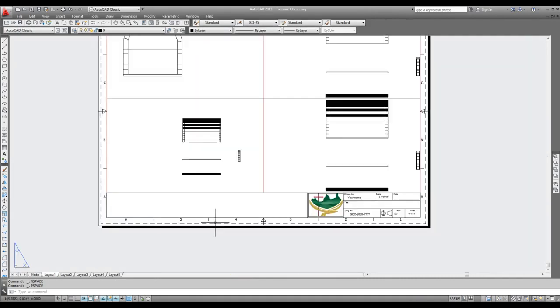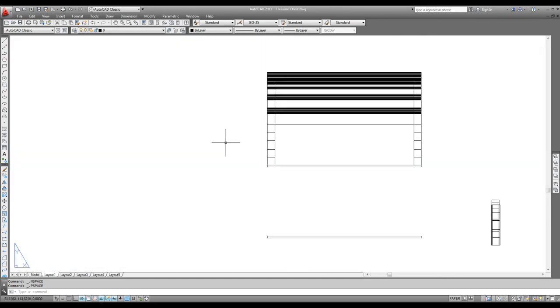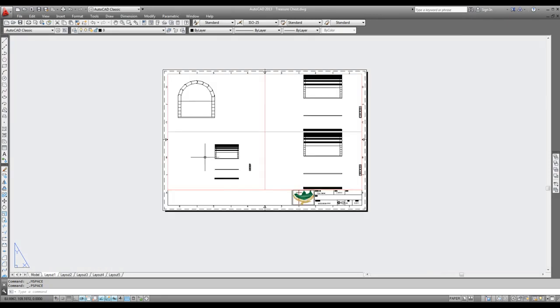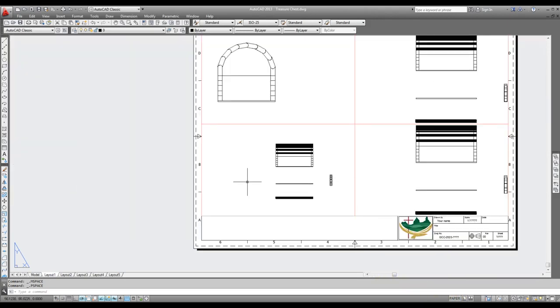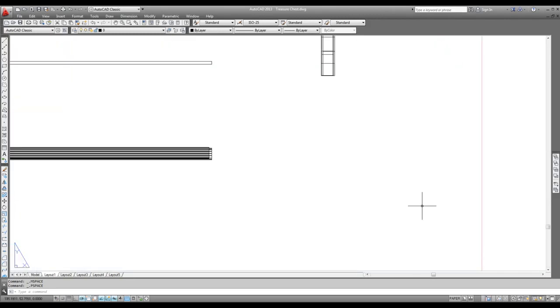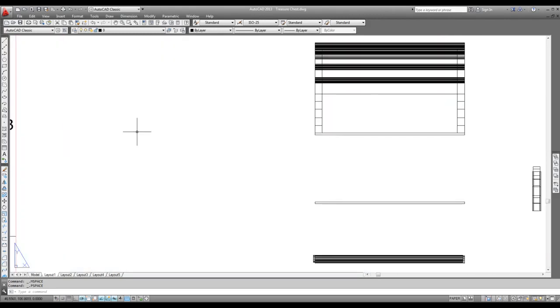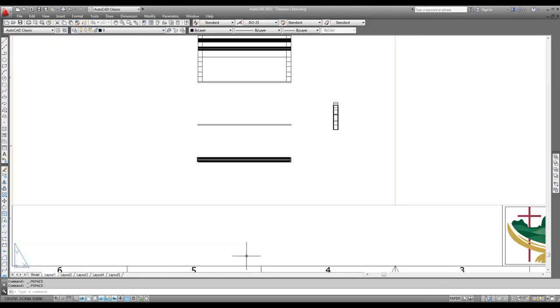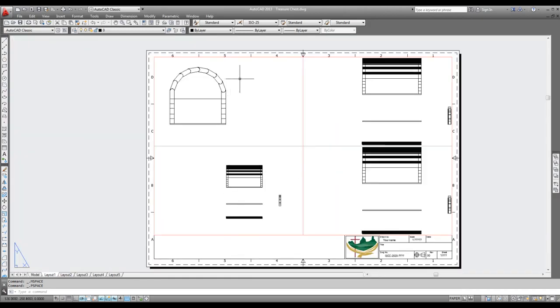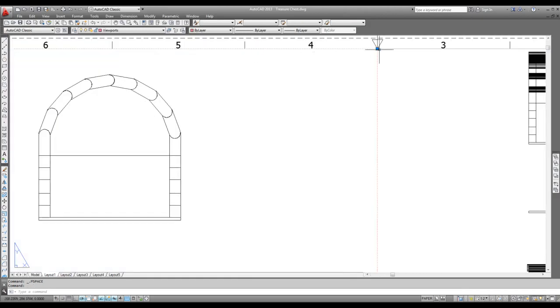So the issue I had once a long time ago is I made my viewport so big, I was in the viewport and I couldn't get out to click outside of paper space, and I couldn't see this one, and I got stuck. I eventually found it, but it's just something to remember: don't zoom up so much that you can't see anything around your model space when you're on the piece of paper, or always remember this one down here. That's just a little tip. I got stuck with it once. I haven't forgotten it either.